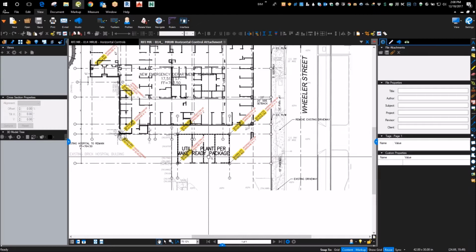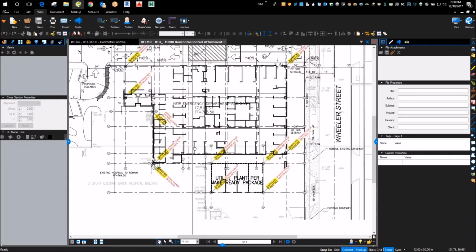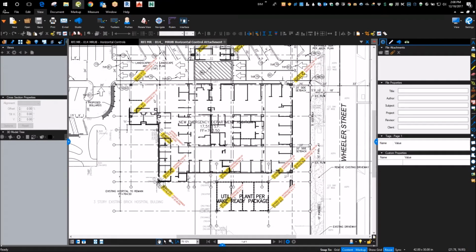And it's good that we're starting to do that, because the plumber out there noticed a bust and said, hey, I think there's a problem with the grid the survey laid out. He asked, can you check it? I checked it, and sure enough, he had laid out the entire building 4 inches east and 4 inches south. So his question on our GoToMeeting, once we showed him the problem, was, should we just shift the whole building?